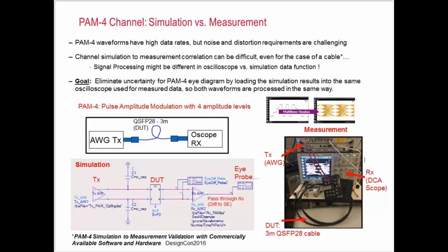It's going to be a lot easier to close 1/3 of the eye diagram than it is to close the entire eye. So one thing that's really necessary to do for these types of signals is the channel simulation. Channel simulation is where you take this signal and send it through some type of physical medium, whatever that is, whether it's a cable or a board or anything.